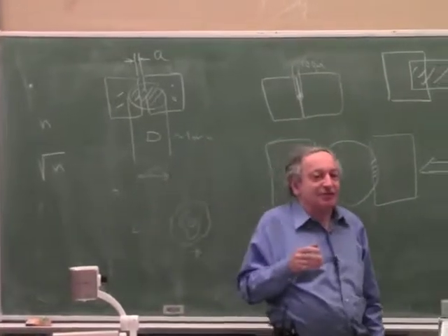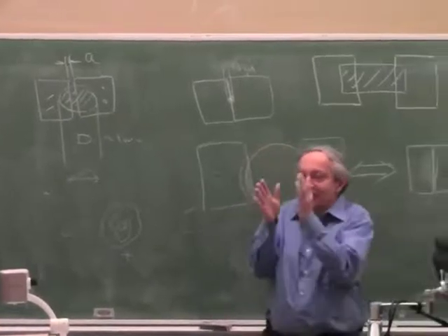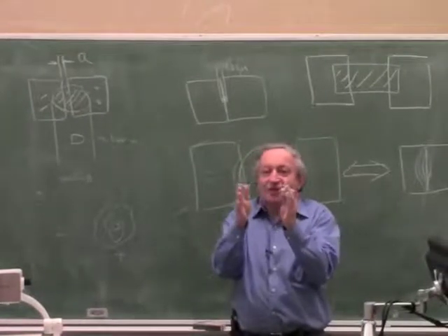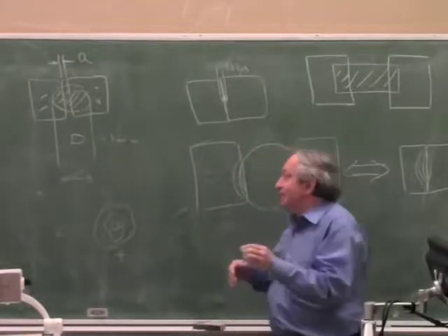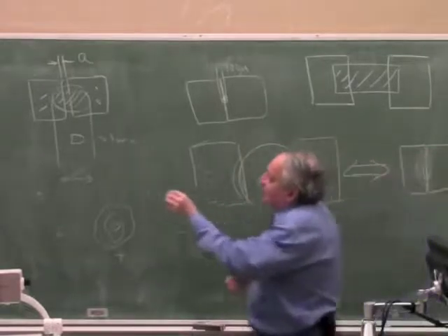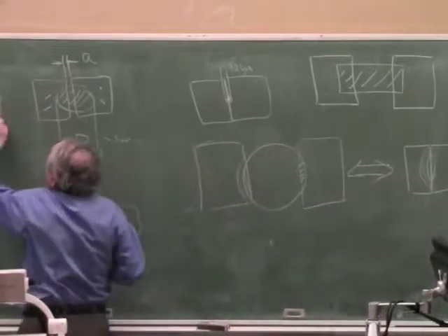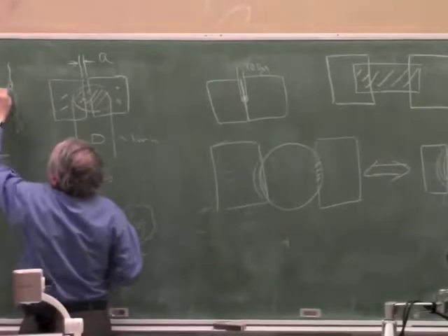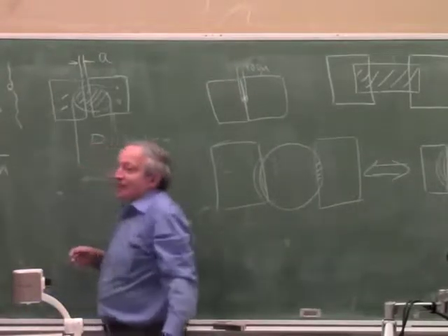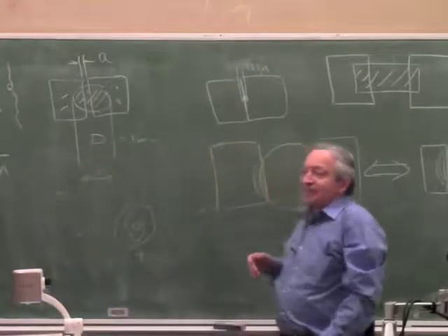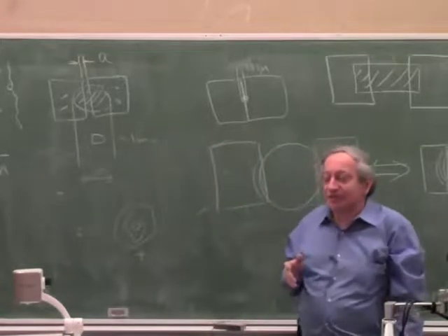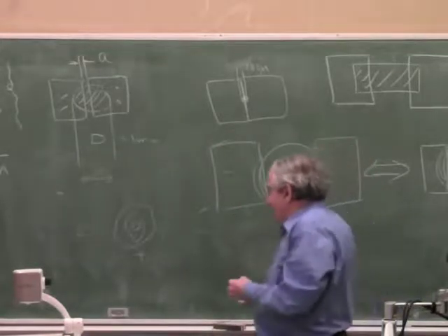In a capacitive sensor, you're averaging, because you have a big area moving, two big plates. You're averaging the signal from the whole plate. So in a capacitive sensor, if the plates are imperfect, which they are, and there is a piece of dust sitting here, you average over the whole area. Okay? Now, the same thing is true for optical sensors. The way to get accuracy is a lot of averaging.